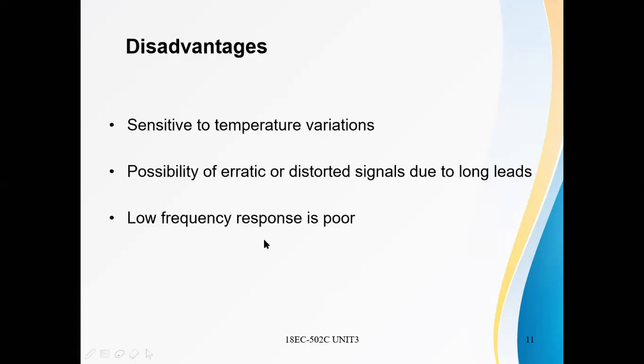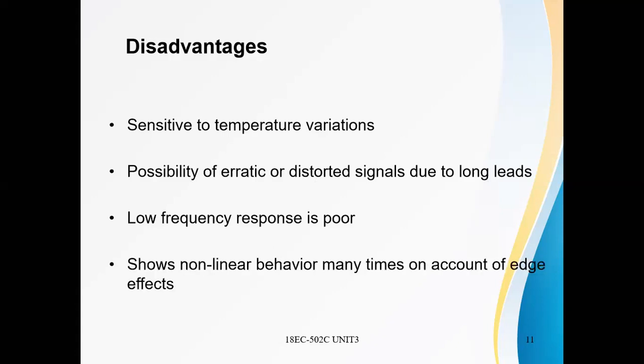Low frequency response: for low frequencies, the response is poor. It shows non-linear behavior. The behavior of this capacitive transducer is non-linear on account of edge effects. Due to the edge effects, there will be non-linear behavior in this capacitive transducer.